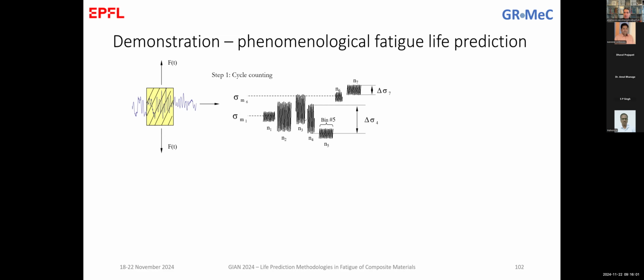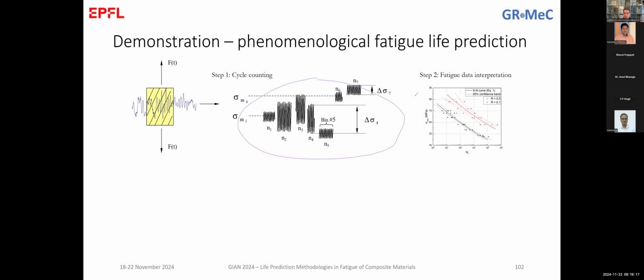The second thing I need to do after this is perform experiments to estimate material properties. If you see an inconsistency between these two plots, so between this one and this one, the idea here is to do tests that will allow me to estimate partial damage factors for each one of these loadings.